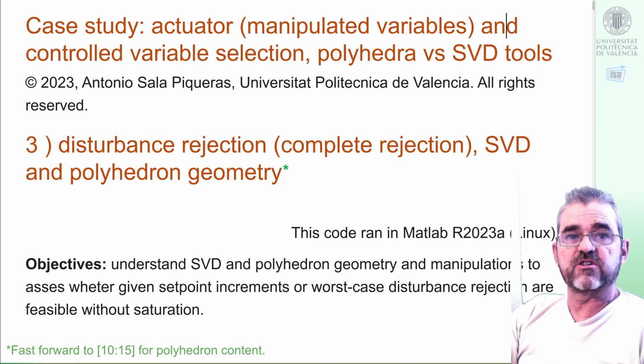So this computation gives the feed-forward element that, if disturbances were measurable, we could directly implement to cancel their effect. Inputs to this feed-forward matrix are the two measured disturbances, and outputs are the 3 inputs in scaled units. So we are assuming that disturbances range in the unit circle, 2-dimensional, in the SVD geometry, and the inputs must not get out of the unit sphere in 3D geometry with these scaled units.